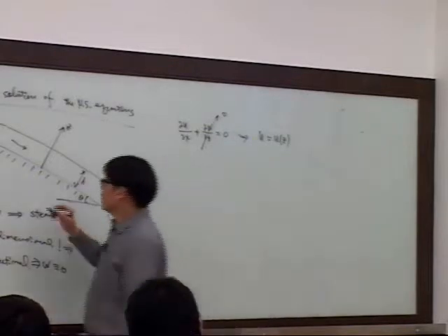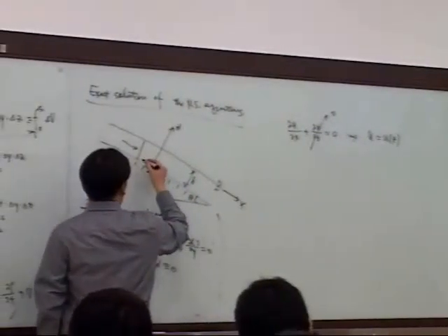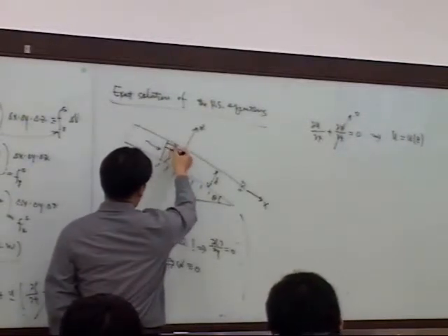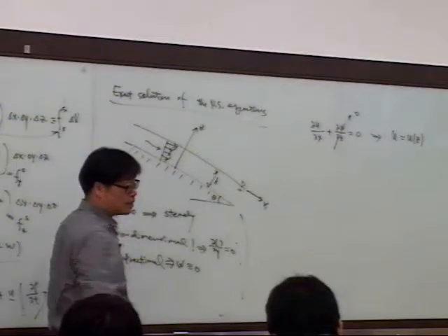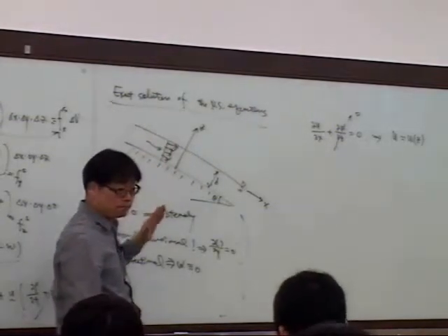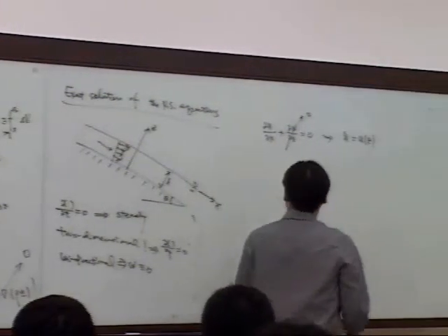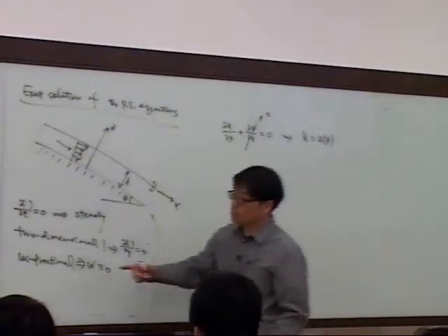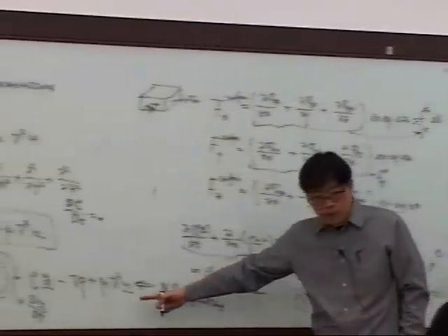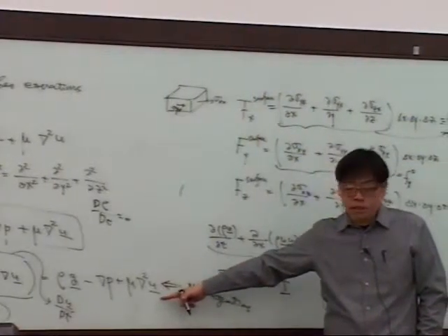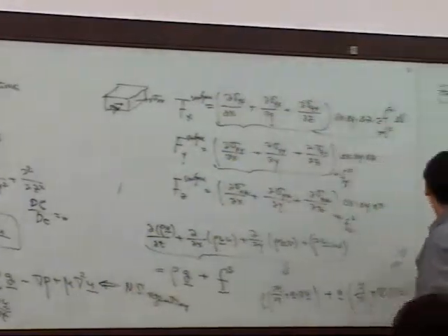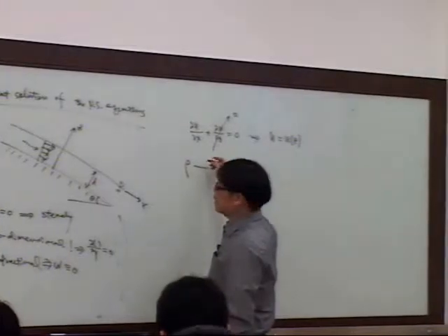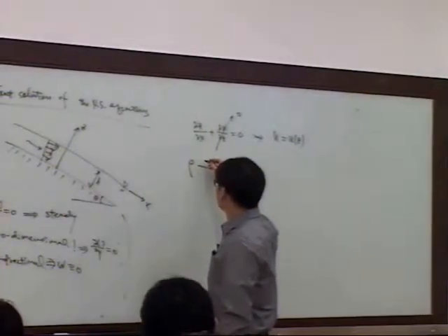If you look at the vertical velocity profile, it will change in z like this. We'll find the solution, but it looks like this. It will only depend on z. So that's what we got. Then we have to write the equation in the x component, because v is 0 and w is 0. It's unidirectional. So all I have to do is write the x component of the Navier-Stokes equation.